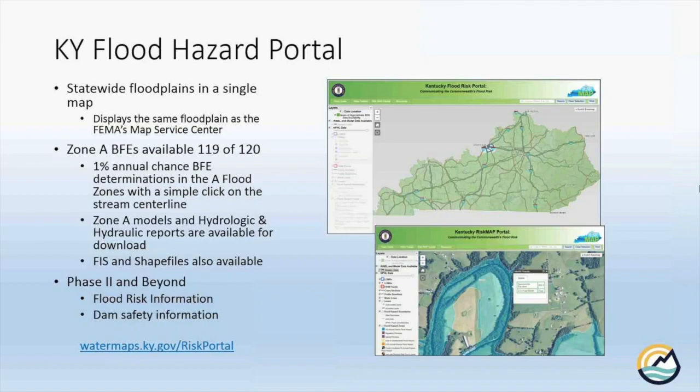So I mentioned before, the flood insurance rate map has base flood elevations and AE zones actually shown on the map. Or if they're not shown on the map, you can go to that flood insurance study, the stream profiles, and actually figure out what the elevation is for your site. But what about when you get out of those areas? What about when you get off the big rivers or out of the cities and get out into the counties?